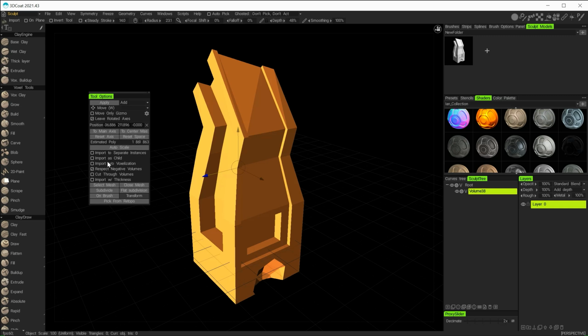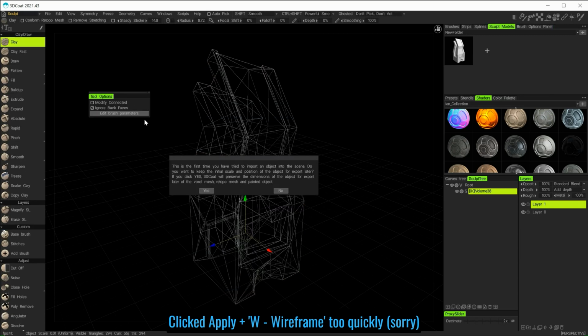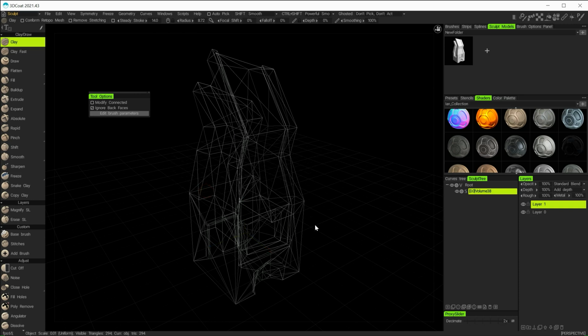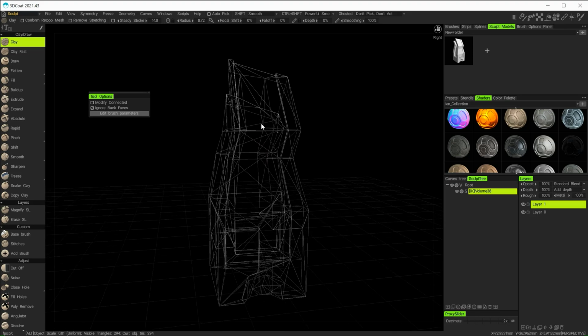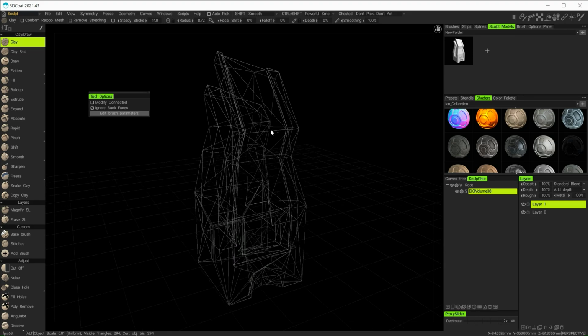What I'm going to do at first is just deselect that one and actually select this one. So it's now going to import this object as a surface or polygon object. And we'll do that simply by clicking Add. Also notice that the same options here that we had in the other room are available to me in here, which means I can go on Boolean cutting these in. So having selected that one, I'll say yes. And you'll notice it's just gone into wireframe mode to show me that this object is now a low polygon object inside this Sculpt workspace.